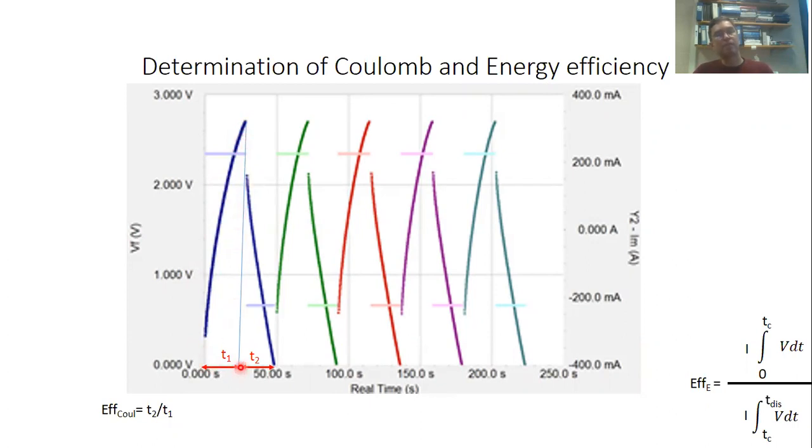Now the integral under the discharge curve is nothing else but the voltage times the time during discharge. When I multiply that with the constant current with which I discharge, then I measure the energy that I retrieve from the capacitor as I discharge it.